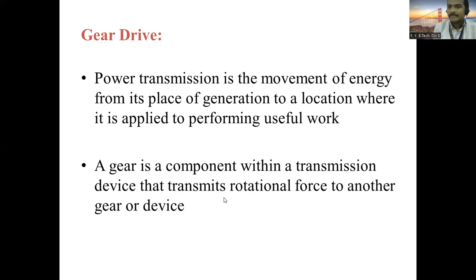You may know. Because the teeth are cut on a hobbing machine. It is also called the hobbing operation. So gear hobbing we can carry out for cutting the teeth on the gear blank. That is why it is one of the complicated parts of manufacturing.